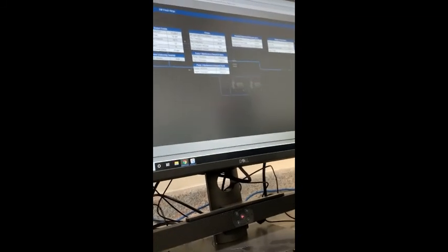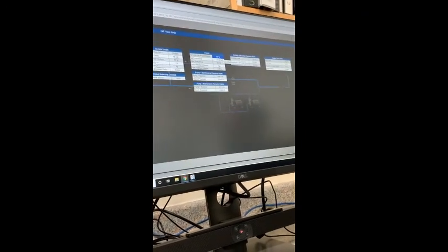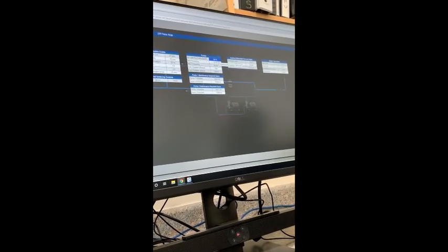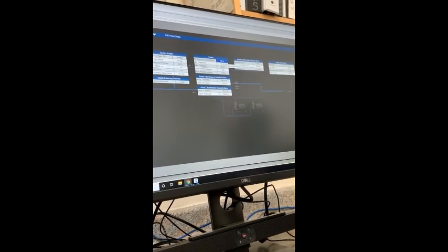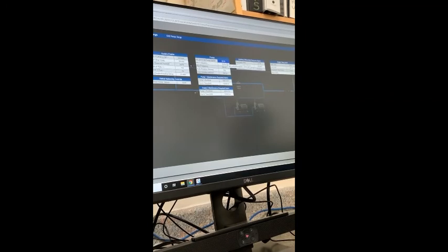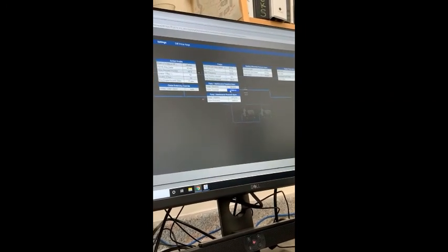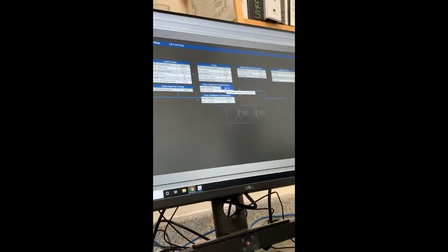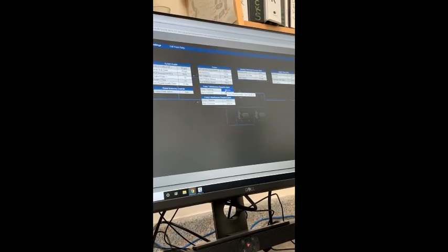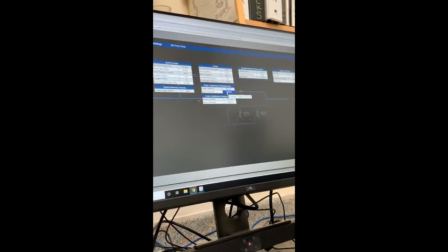Here we have, if the DP COM fails, the pumps will automatically just run at 50% speed, just because it's basically a speed where we're not going to overpressurize. We may not be running efficiently, but we'll make sure that everyone's getting the water that they need. And then again, there's a maintenance reminder for the pumps. Right now they're set to 10,000 hours.